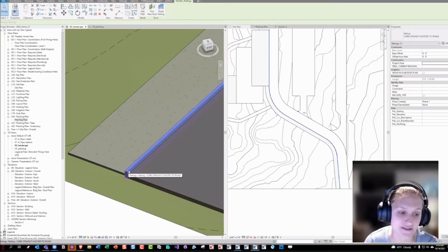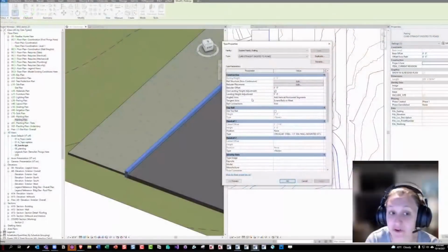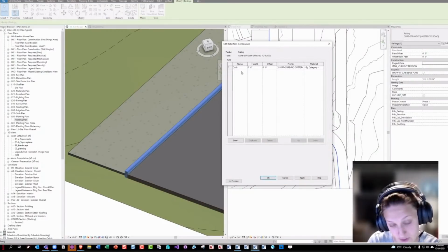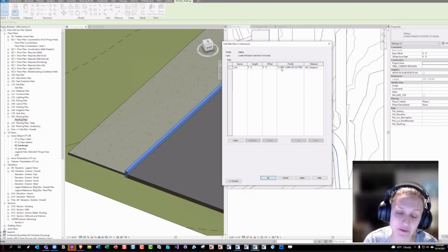We'll look at this railing here for a second. One of the out of the box tricks that I've learned, even when developing this tool, is that railings are actually more stable if you use the non-continuous rail as opposed to the top rail or a handrail, which is the older version of the rail profile. The old school profile is more stable. It will give you fewer errors and it behaves a little better on weird conditions, which you can get lots of.